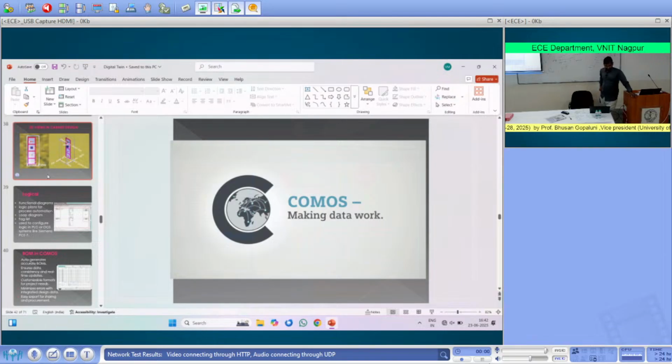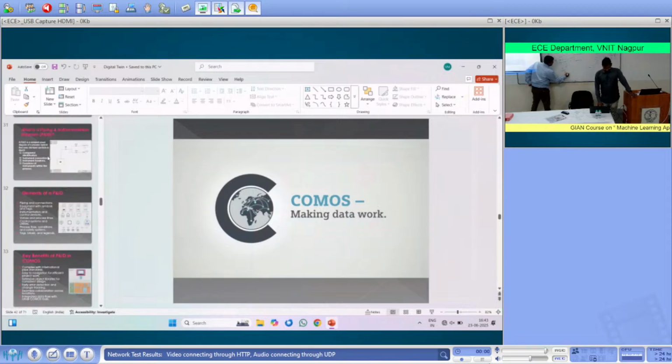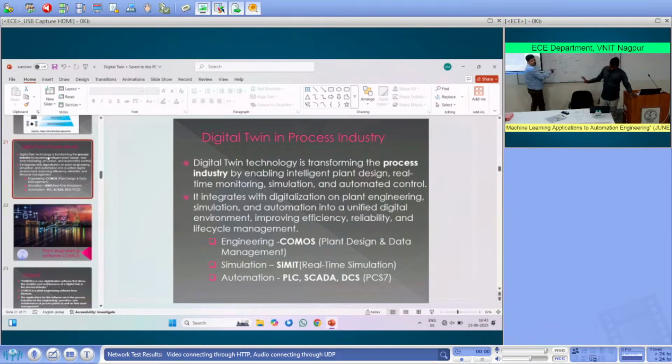We know the equation for the square tank: A dx/dt equals input minus output. The differential equation will come like this. Area is going to be a square tank, so it will be A into B into H. So it will be very easy. But when it goes to a spherical or conical tank, the height will be different, but the parameters are all the same. Is it clear? So that's what I'm asking.